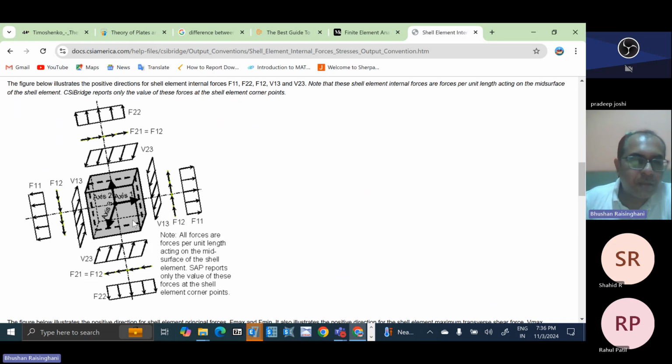So based on the equilibrium diagram, you can see positive, negative signs here on the 3D object on which the forces are getting generated. For the 3D element, this is the realistic description of the forces. We are eliminating V in many cases because that is not the dominant force. Bending and axial forces are what we are modeling, not in the shear direction V.